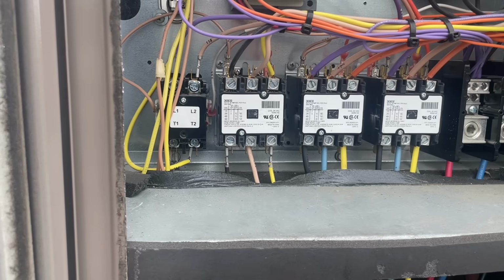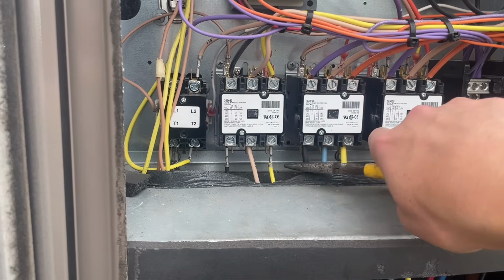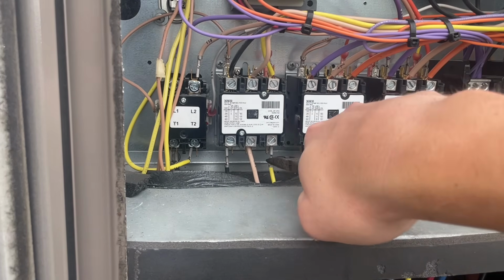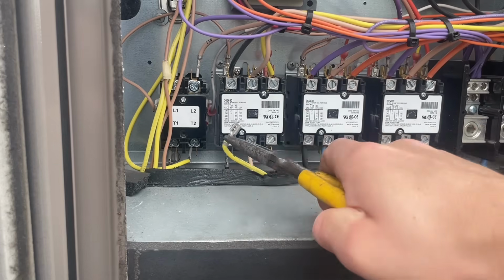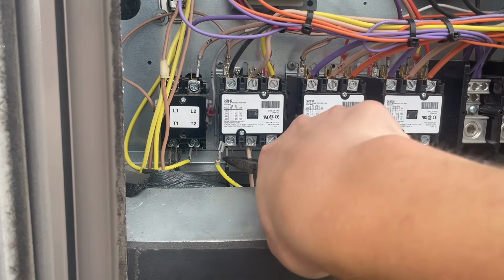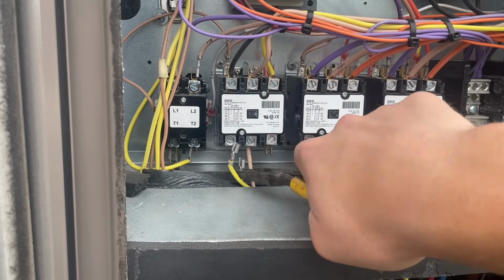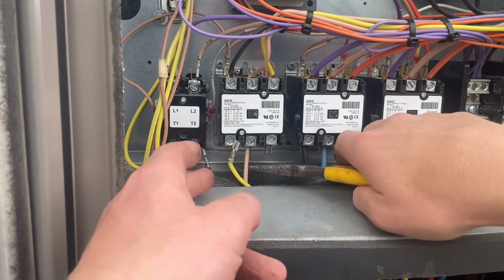Now, as I promised before, I'm going to put the motor in the wrong direction, and I'll show you how to do that and resolve it. All you're going to do is take any 2 of your leads. So in this case, we're going to use yellow and black because they're the easiest to get to. We don't need a screwdriver. They're just spades. And we're going to reverse them.